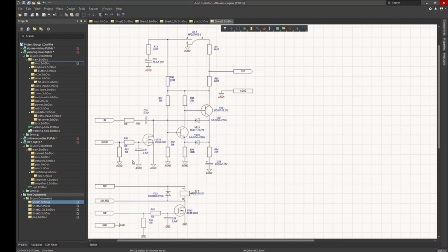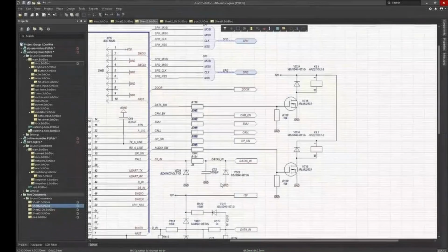Have you ever caught errors in typical schematics from data sheets or the internet? It happened to me a couple of times. Now, all the schematics that I take from the internet or from other projects, I put through a test. Either assemble them on a breadboard or run them in a circuit simulator.